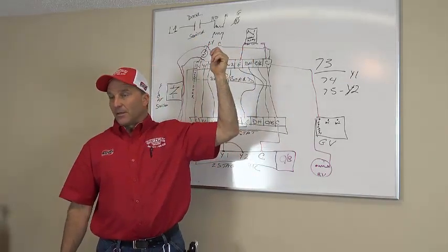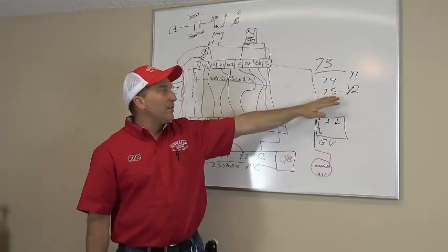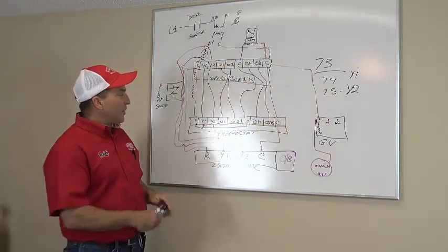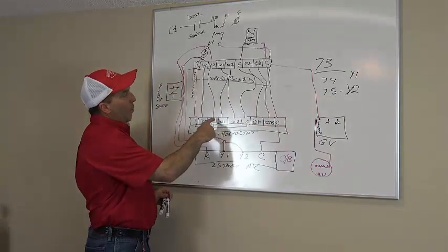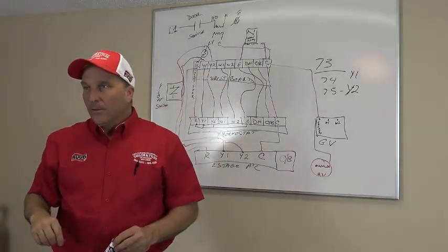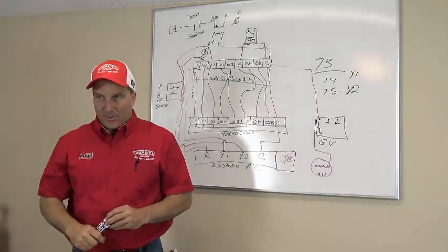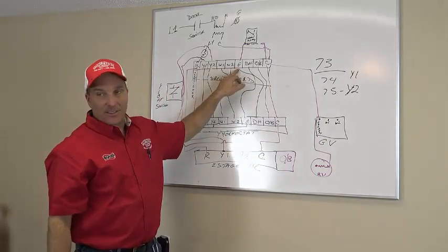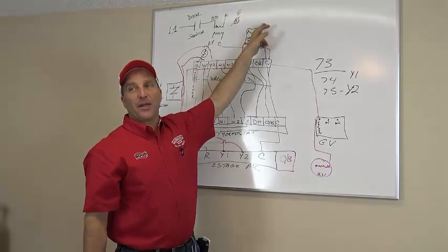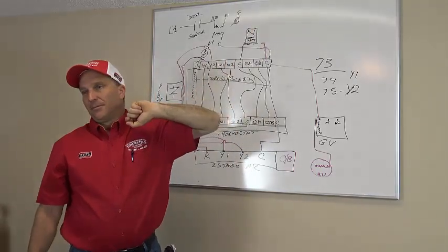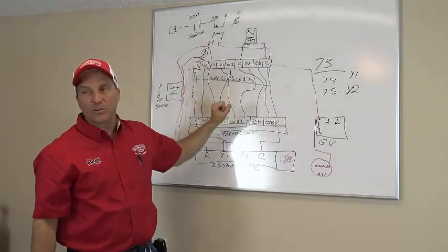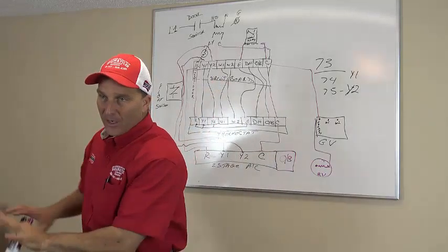Make sense? Okay. Now I go to 75 degrees and second stage kicks on. What happens? Then I energize Y2. Y2 energizes the Y on my circuit board. When Y energizes on my circuit board, it de-energizes G and energizes the fan relay to turn on high speed for my fan. It's just a different relay wired into the circuit board, not a separate relay out anywhere, okay?